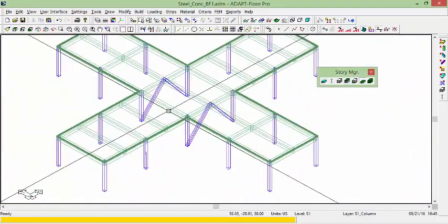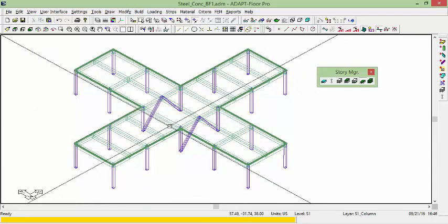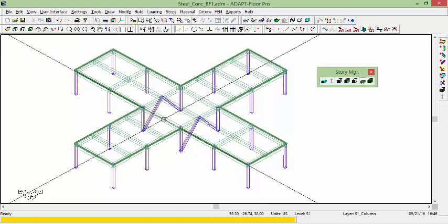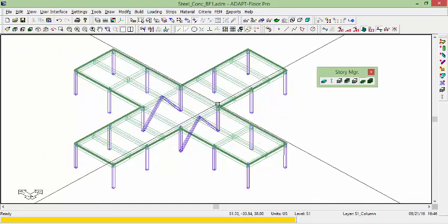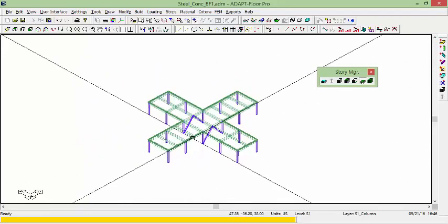Now it's clear that for this particular steel structure, we would need a lateral resisting system in the Y direction. We're not going to model the braces in the Y. We're just assuming we're looking at the X direction, but we might have the same configuration of braces in this bay here and this bay right there. We've now established the first level of the steel structure.